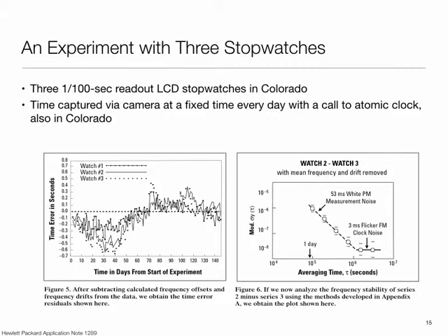One thing you can do is measure the long-term drift, the average frequency error, and subtract that out. What you would then be left with is the changes in frequency around that mean. Once you do that, you can begin to look at what the short-term variations are. There are many different ways of examining this data, but one has to worry about how the underlying clock frequency is changing and compensate for that somehow. And that is what synchronization protocols do.